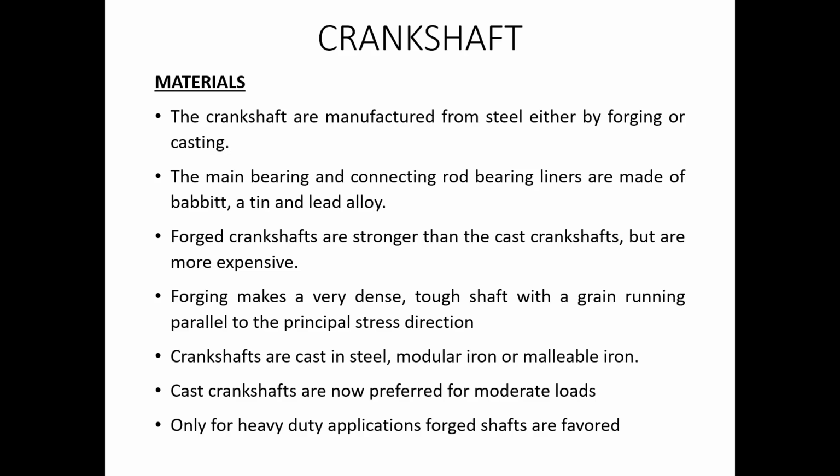And it makes the material very dense in nature, because the grain structure of the material that undergoes forging becomes a very dense structure. The grain structure is deformed and the grains come very close to each other and reach a stage where further deformation of the material cannot take place. So it is very dense and tough.